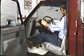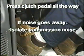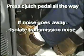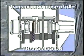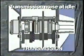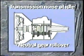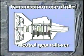The next test you can perform is to press the clutch pedal all the way in. If the noise goes away when the clutch is completely disengaged, then you can suspect the problem is in the transmission, not the clutch. Several things may cause transmission noise at idle when in neutral: input or counter shaft bearings, output shaft pilot bearing, the input shaft and counter shaft drive gears, or neutral gear rollover. When the gears are not under load at idle, the loose meshing of the gear teeth causes neutral gear rollover. The noise may be more pronounced in heavy-duty transmissions and transaxles.